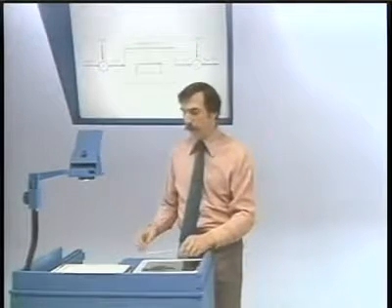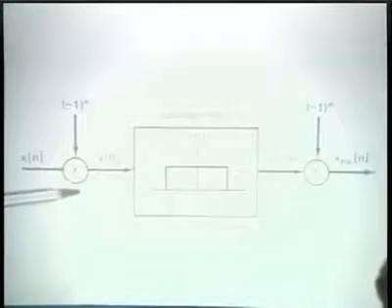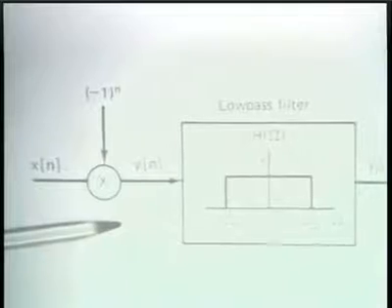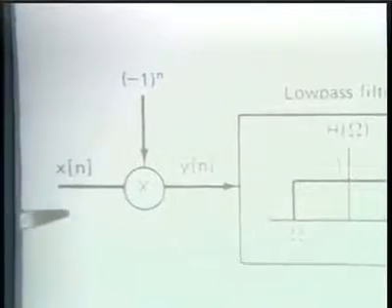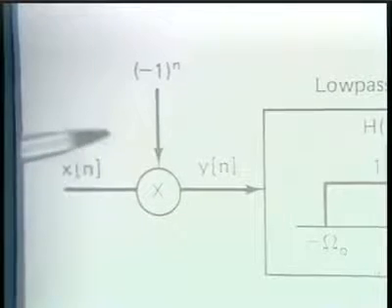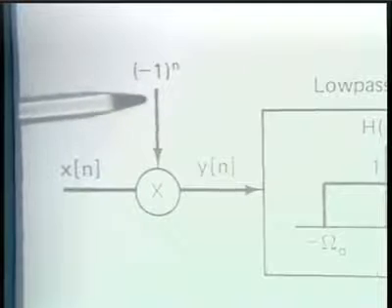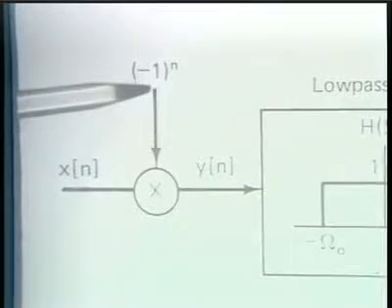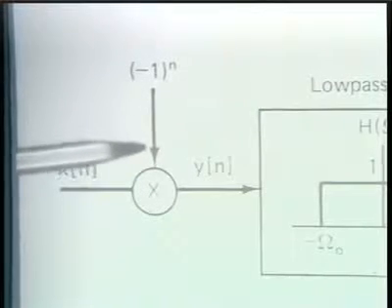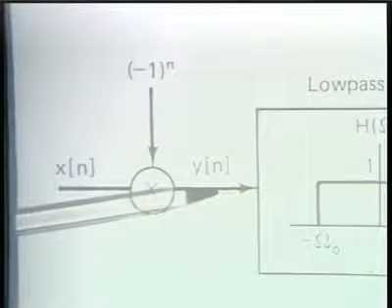We had originally talked about this when we introduced the modulation property, in the context of converting a low-pass filter to a high-pass filter. And the notion was that if we modulate the signal with a carrier which is (-1)^n, and that's simply a complex exponential or sinusoidal carrier with a carrier frequency of pi, then that, in effect, interchanges the low frequencies and the high frequencies.